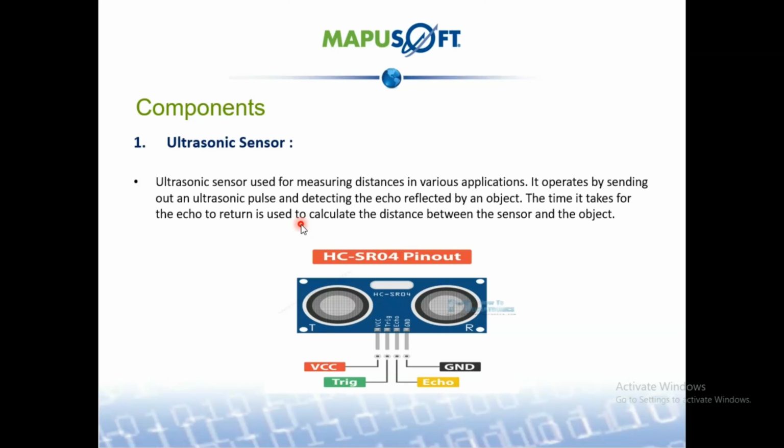Ultrasonic sensors are mounted on top of the garbage bin to measure the distance of the waste. As the garbage fills up, the distance to the waste decreases, allowing the system to determine when the bin is full. The control logic which governs this monitoring process is simulated on the RTOS running on a host machine, allowing developers to test and refine the system.